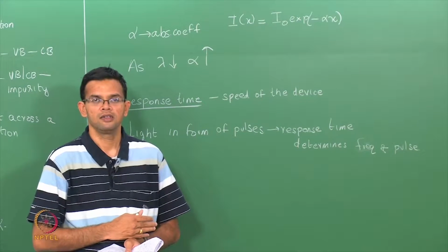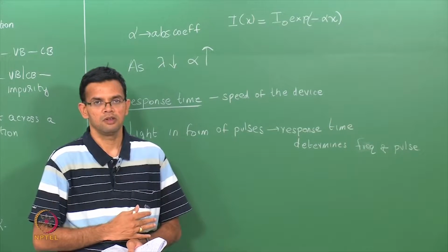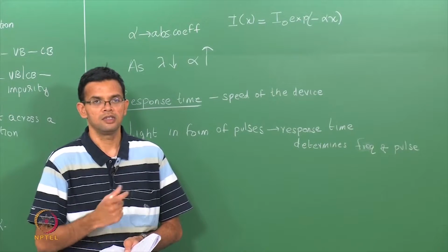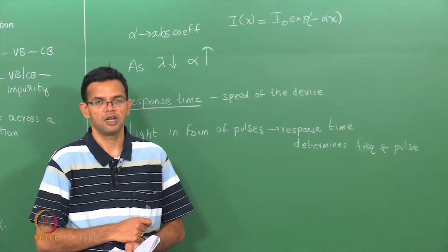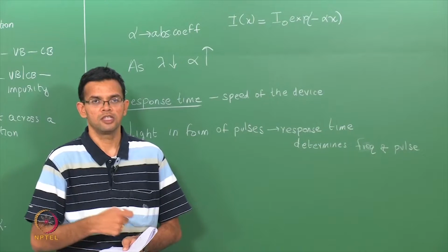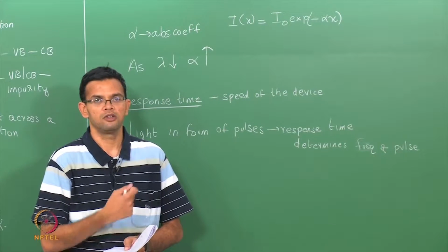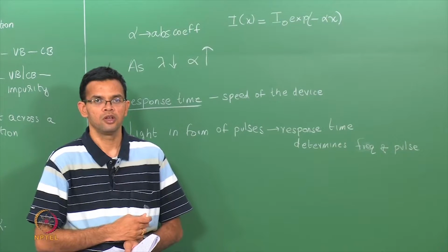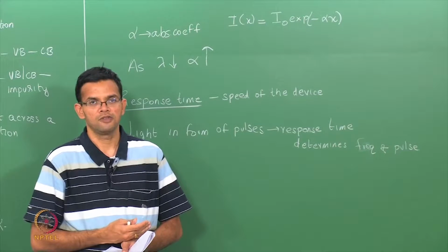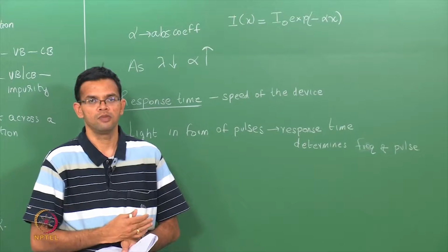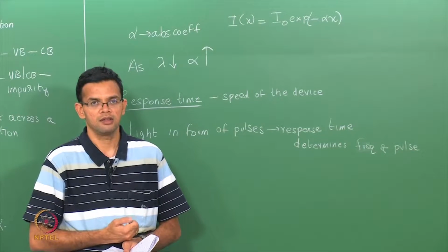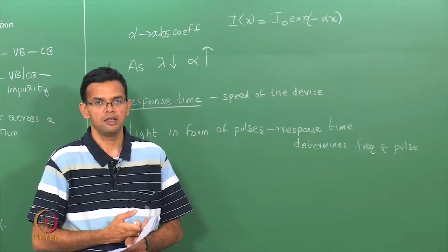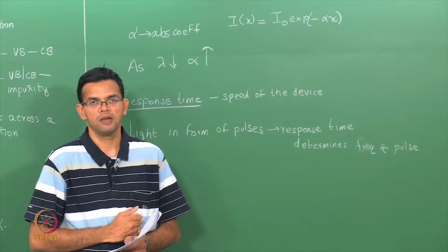On the other hand, if you have a p-n junction with a very short depletion region, then the distance the electrons and holes have to travel is small, so that the response time is fast, but the drawback is the number of electrons and holes generated is small, so that you need a large amount of signal in order to be able to detect the radiation. So, there are different trade-offs depending upon the design of the device and the response time that is required.